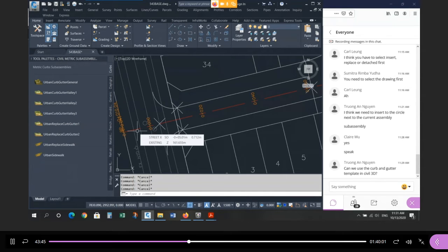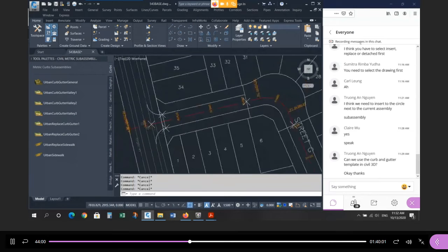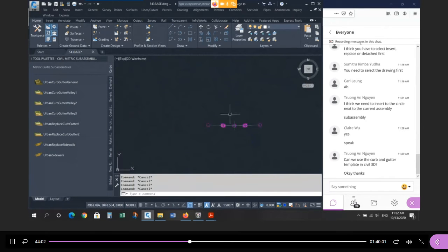Okay, so I'm not going to use my corridor to do any quantity, granular asphalt. I'm not going to do my estimate that way. Okay, and in this course, we're not doing any estimating. We're just going to design. Next semester, we're going to use the same technique. We're only going to draw the finished ground. So if I go back to the cross section, right, nothing underground. It's just the finished ground, the surface you would walk on or drive on.